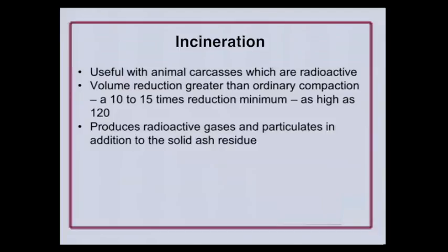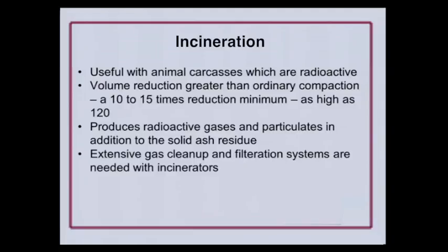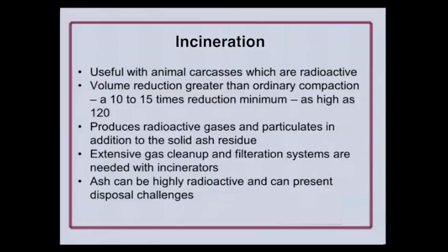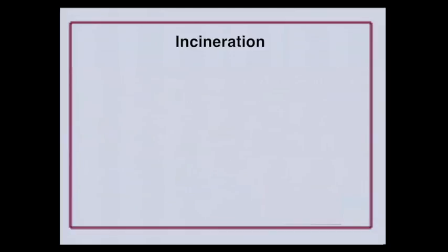That does produce radioactive gases and particulate in addition to the solid ash residue. So all of that has to be addressed in the technology. You've got to have gas cleanup, filtration systems. The ash can be highly radioactive, as we just said, because of the concentration effect. And so you have that disposal challenge that you have to take care of.